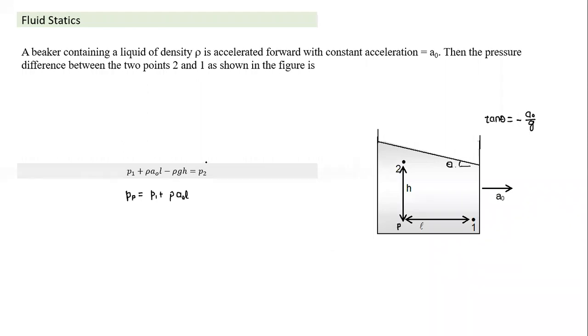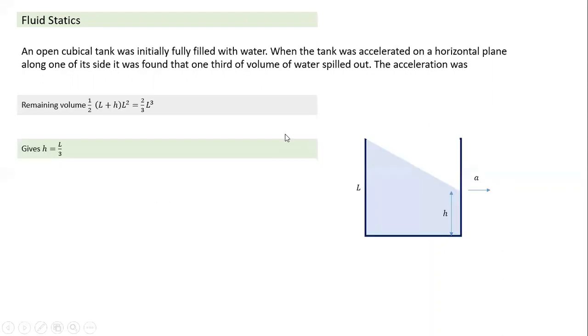So that is something similar to what we do in the case of Kirchhoff's rule. Very similar, with a starting point. There also we track potential. Here also we are tracking pressure. In a very similar way, this is how we can find it. And this expression we come to in the case of horizontal plus vertical acceleration. So it's a very simple application of change in pressure due to horizontal acceleration, which, similar to minus rho GH, is equal to rho into A into delta X.